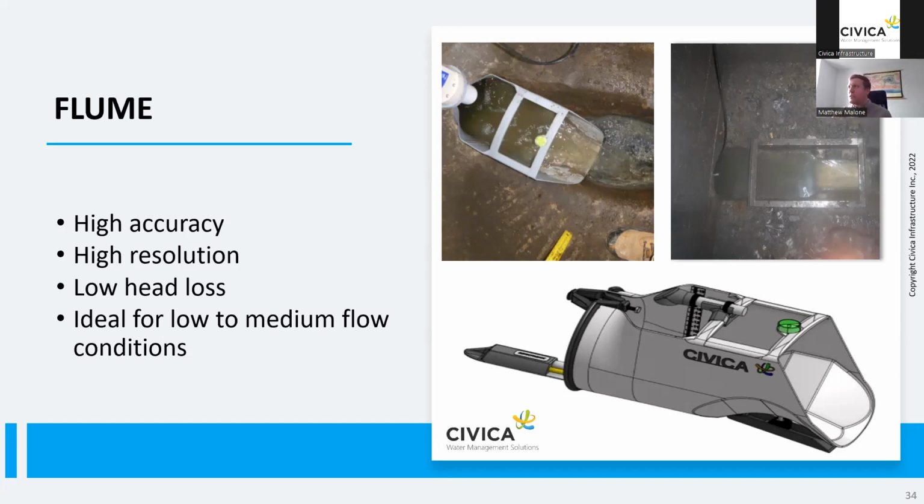As I said, once you get really high flow or surcharging in these situations, the flow will go above the flume, and then the relationship of depth and flow across the flume obviously falls apart at that point.